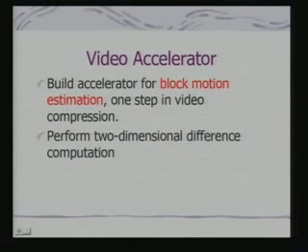In fact, with the camera we had discussed the basic principle of image compression. What we do? We apply DCT to the image, then we quantize, then we do entropy coding. When we are having a video camera, for that matter, we would like to design one which would store MPEG videos in the memory stick, then we need to implement in hardware the MPEG compression scheme. The MPEG compression scheme is conceptually similar to that of JPEG in various ways.